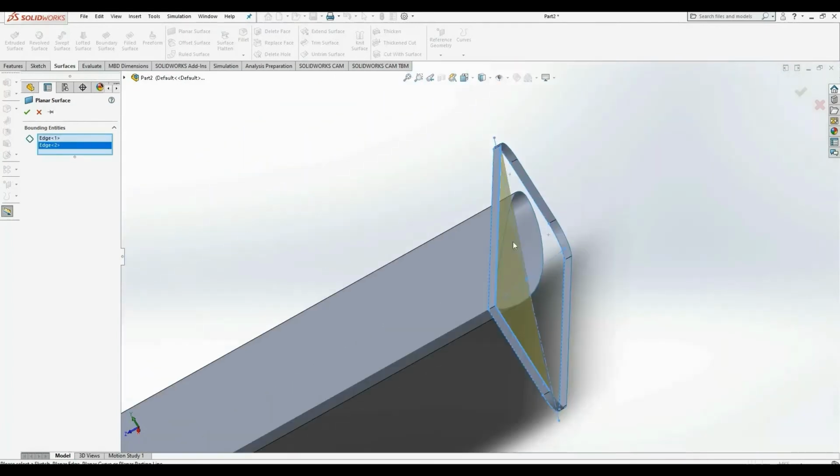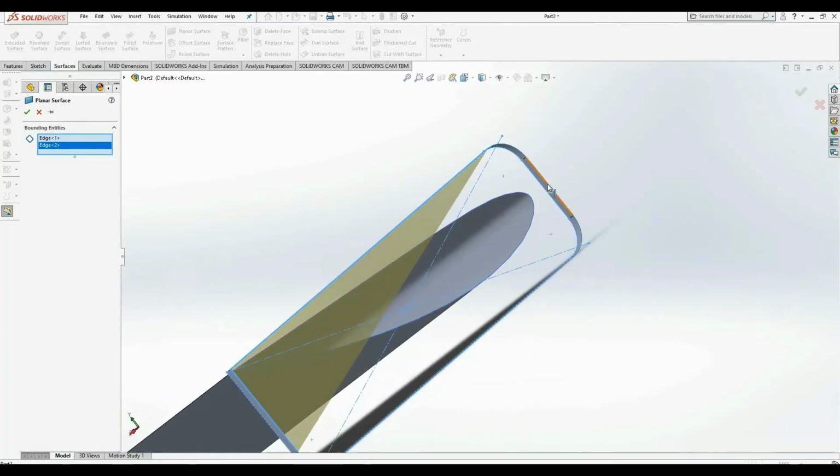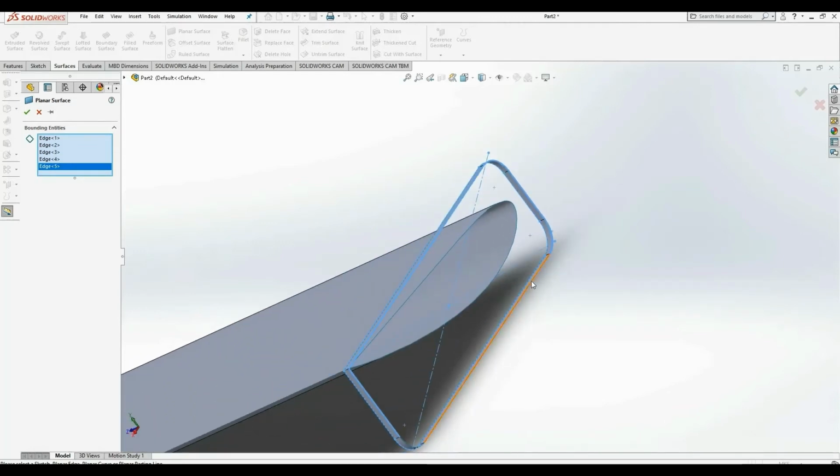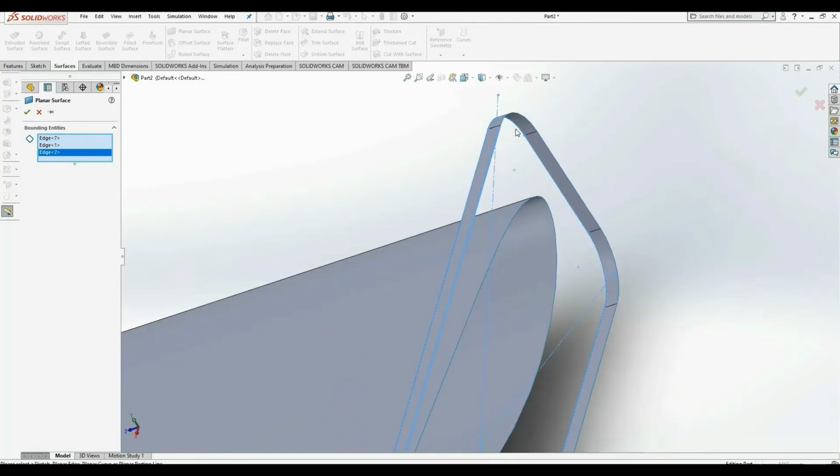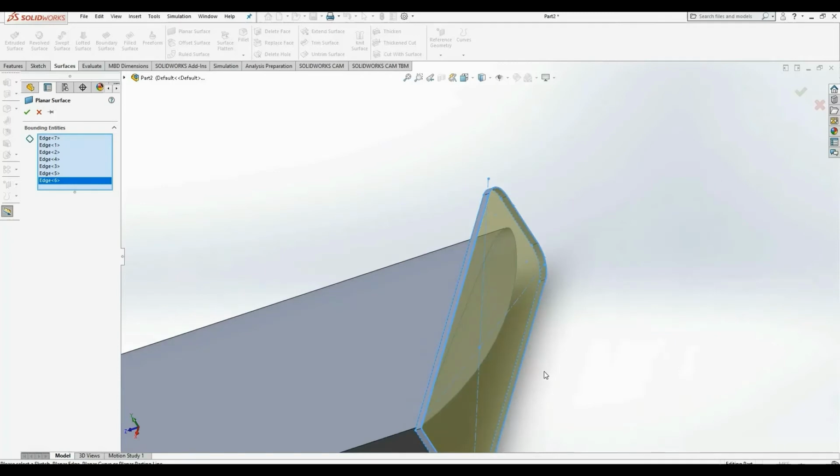When I'm pressing, as you can see, it started to build it and then it disappeared. The reason for that is the surface tool needs you to follow a logical path. If it's not logical, it won't preview the surface. So let's start that again, one edge at a time in a common clockwise format. In this case, you go anti-clockwise, as long as each individual edge that we are choosing is next to the next piece, then it also fills it, so we know we've cracked it.